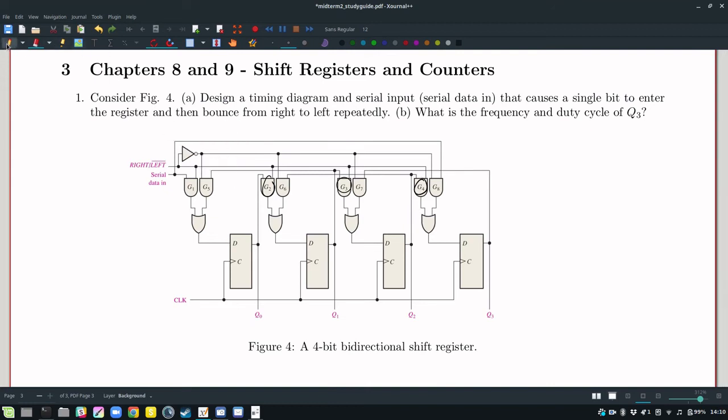these gates are used. So the right-hand gates of all the pairs. And so the serial in line, if this is low, G1 would be blocked, and serial in would go all the way through that top line, all the way to G8. And then where would the next data bit come from in this flip-flop? We have to follow the trail. So it would come through G7.